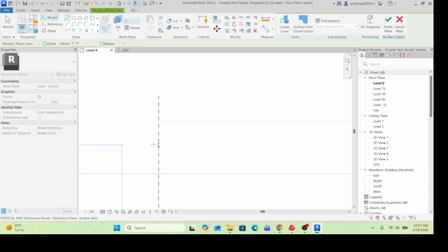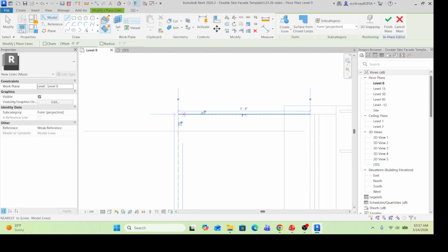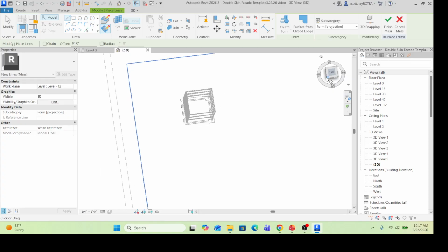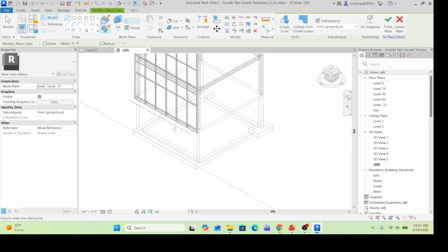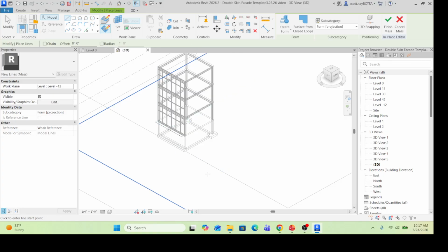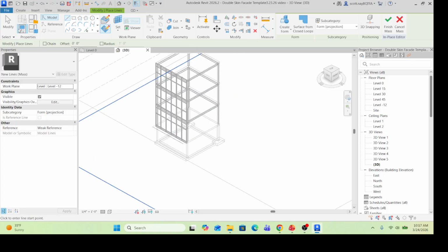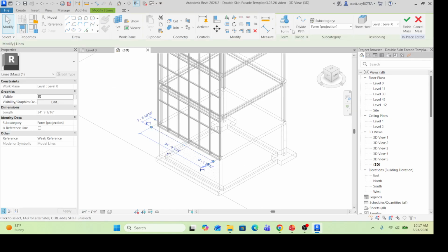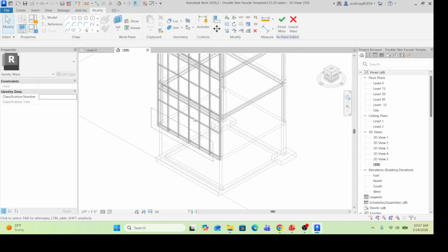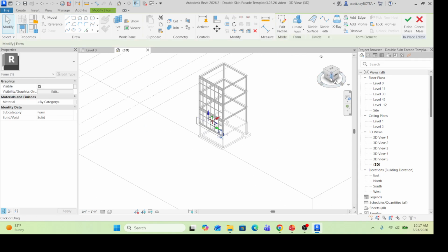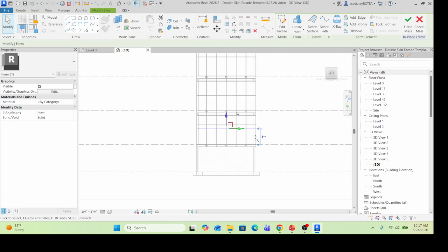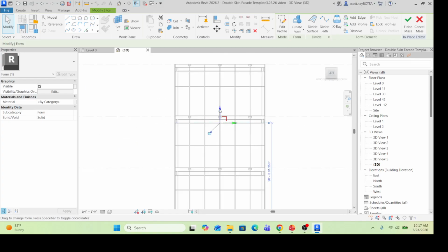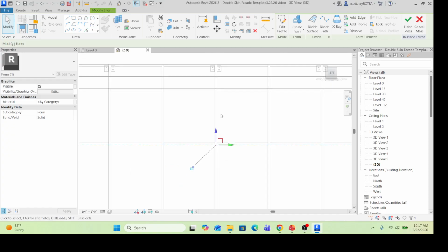And you might be tempted to say, well, I don't want to use the shape handles, I want to come drag it all the way up. But what can happen is Revit can misinterpret multiple lines and create a big circle around the building. So unfortunately, the most reliable way is just to click on it, say create solid form. And now you'll see, because it's straight, at least it will snap into place.